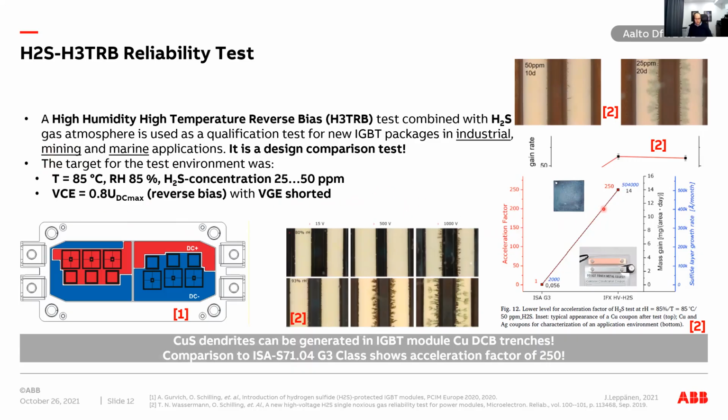Because in literature it is seen that moisture can actually prohibit this gas penetration, because typically gases are dissolved into the moisture, and then they would be surrounded by water molecules, and then it would be less easy for them to diffuse through the porous gel.